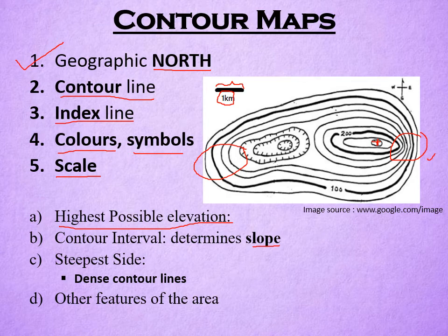So in this part, as contour lines are close to one another, that means the spacing between two successive contour lines is less in distance, that indicates a relatively steeper slope. So this part within this figure indicates a steeper slope, whereas in this part the contour lines are distant from one another, this part indicates a gentle slope for this particular contour map.